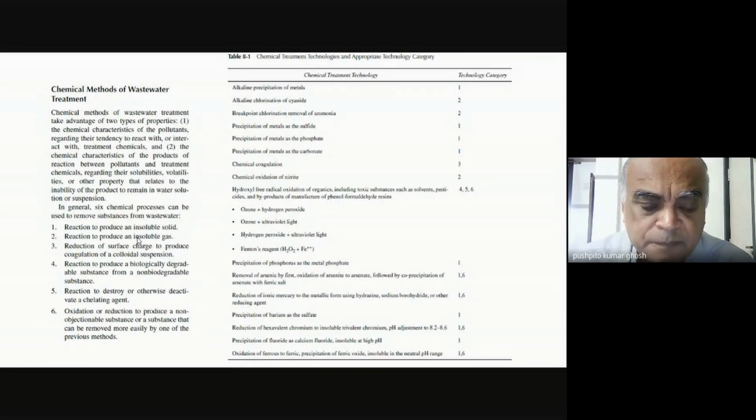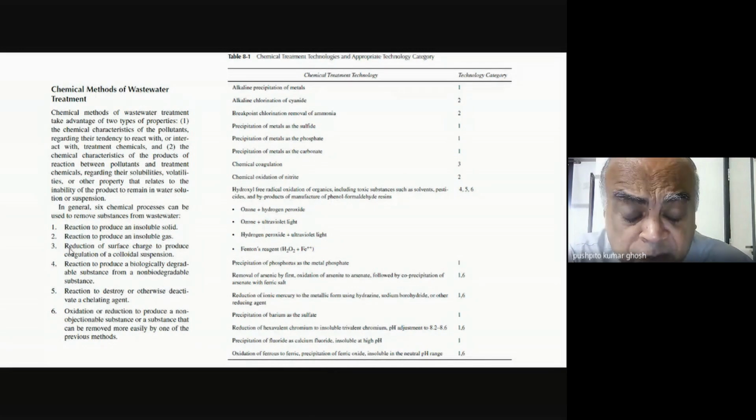It should be harmless. The third is sometimes you'll find that your effluent is actually like a colloidal suspension, and it's not a homogeneous one phase, although it might look like it. In which case you can of course try to do a coagulation. We are quite familiar with the way you can do clarification with alum, for example, so you can look at that as a way of removing suspended matter, finally dispersed suspended matter.